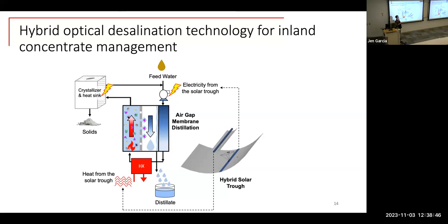And then do you have an idea of the approximate temperature gradient on the two legs? Yeah, so the delta T, the inlet temperatures are the highest points, right? Ideally we operate between 20 to 30 degrees Celsius on the cold side, and we can get the hot side, 50 degrees is like the lowest, up to like 80 is the highest.